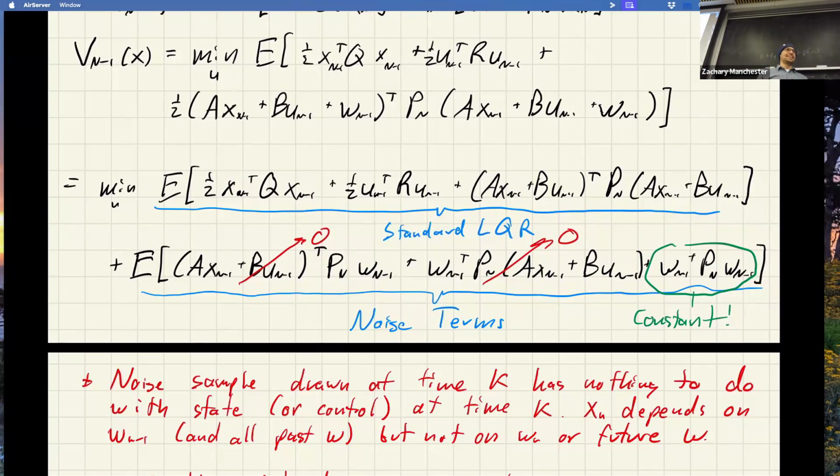then if it's not zero mean Gaussian, right? Then it would be something else. The standard term for that is colored noise. It's noise where there's some time correlation, like there's some underlying dynamics going on. And what you should do in that case is try to put that in the dynamics. So if there was some kind of trend in there that wasn't just pure randomness, you should try to figure out what that is and model it in the dynamics model and estimate it out. And then once you subtract that out, what's left should be Gaussian noise, right?